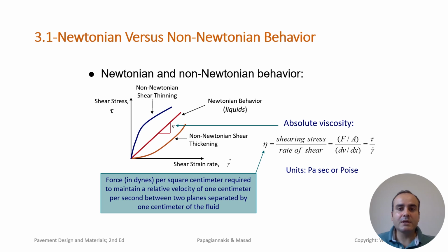At high temperatures, a binder with too low a viscosity could lead to rutting, where the pavement permanently deforms under the weight of traffic. This is often seen during hot summers when the pavement becomes soft and can't hold its shape. On the other hand, at low temperatures, a binder with too high a viscosity could become brittle, resulting in cracking, especially in cold climates. This is a major concern during winter months when the pavement contracts and the binder becomes too stiff to flex.